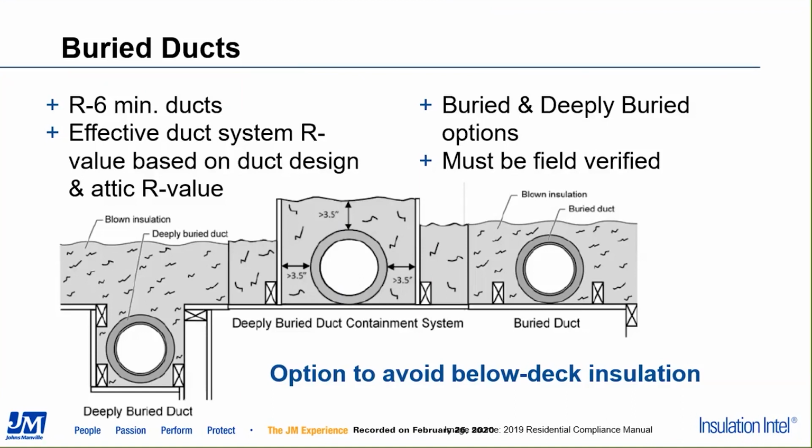If this approach is chosen, it has to be verified in the field. Your HERS rater is going to have to come out and make sure that these channels were actually built, and that there's the correct amount of insulation over the top of the ductwork. Later on, when we talk about examples, we'll show how this benefits in terms of showing compliance to the code.